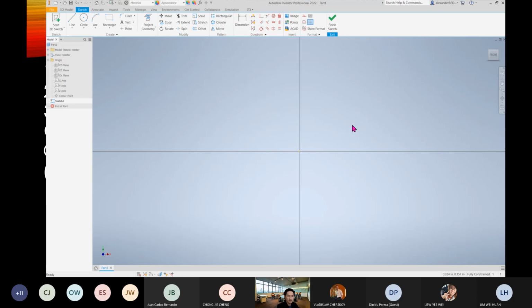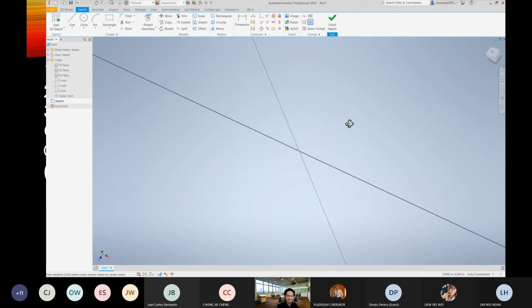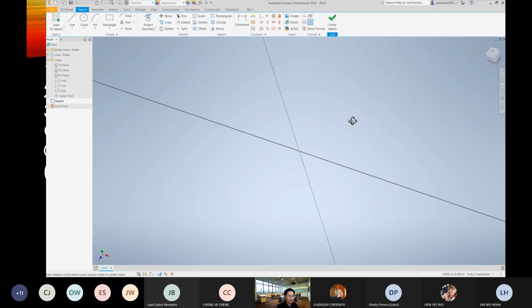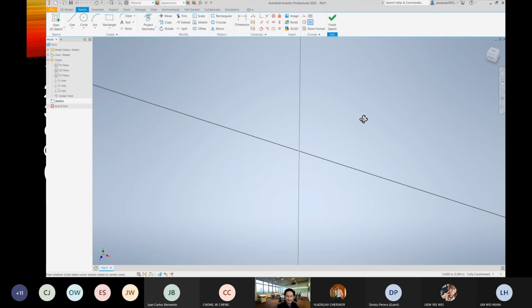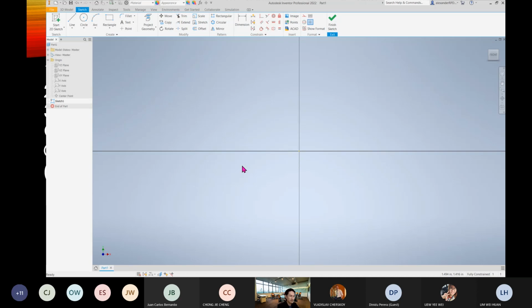When you get in here, there's nothing so magic. If you want to rotate, you can still rotate. Now I'm pressing Shift and also the scroll, and you can see I can still rotate. You don't sketch that way, but some people may prefer sketching in 3D view. It's up to you. So now I want to go back to my 2D view. I click Back Front, then it brings it back over here.